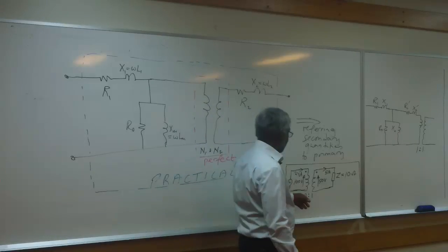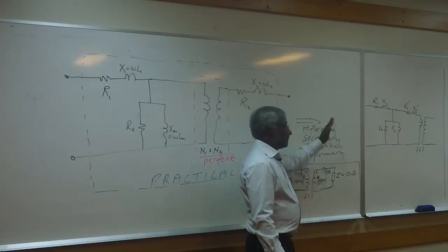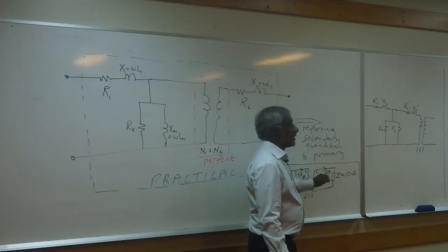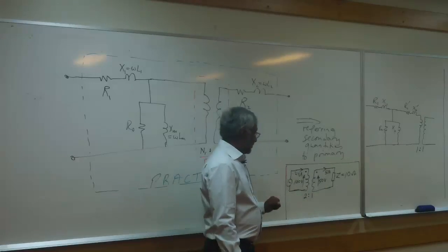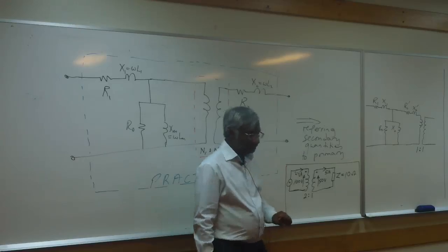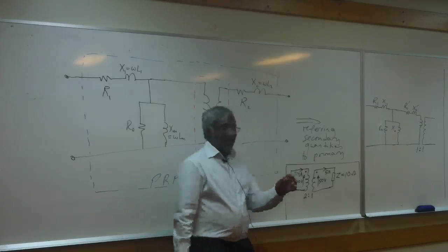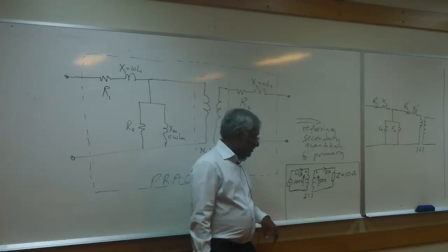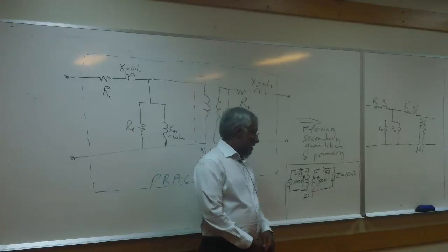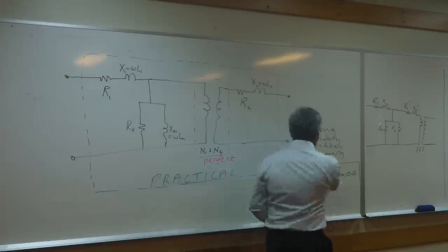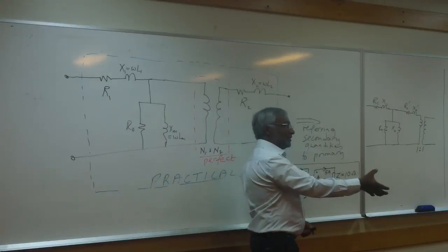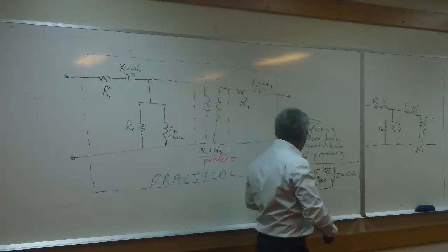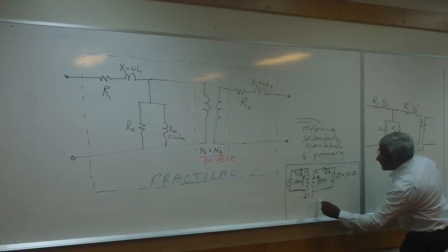In other words, if you are stepping down voltage, you're stepping up current. Voltage has stepped down by factor 2. Current has to step up by factor 2. So that's the situation. Now, I don't want you to do calculations or anything like that. I want you to think. Think about this. If you had this transformer and I was to take it away very quickly, and I were to replace it by this.